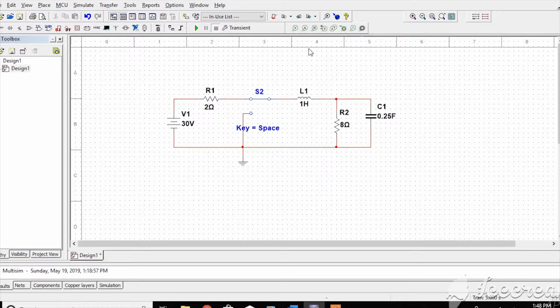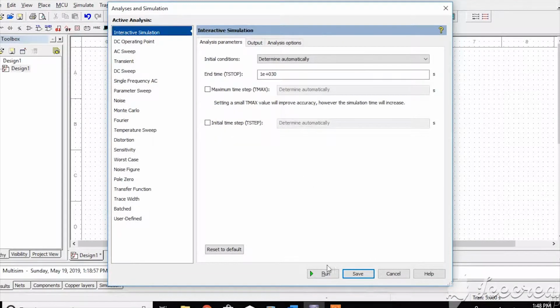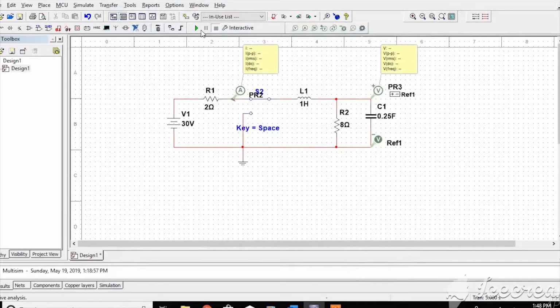To simulate the initial values I0 and V0, just put the current probe after resistance R1 and the differential voltage probe at both capacitor pins. For the underdamped case, we got the initial value I0 as 3 ampere and V0 as 24 volt. To simulate the graph response, just put the voltage probe at the inductor and capacitor pins.